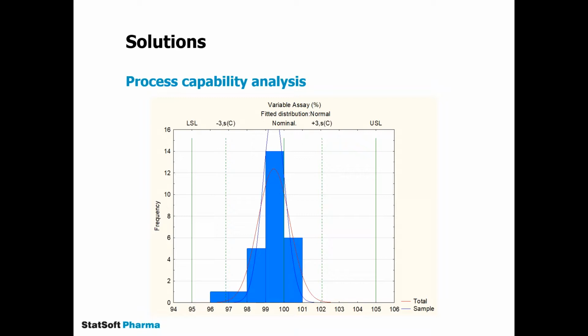Process capability is one of the methods of measuring the effectiveness of a process in meeting specification, as well as measuring process improvement efforts. To determine that, we can use capability charts that consist of a histogram with control and specification limits shown. It allows us to estimate to what extent the analyzed process defined by control limits is within the tolerance limits defined in the quality specification.